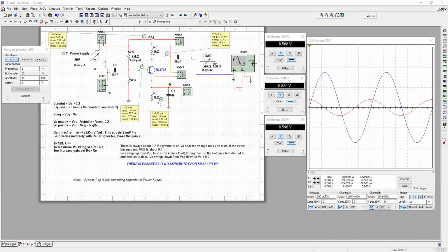We're going to set the current through the BJT using this voltage divider. The voltage at the 5 kilo ohm resistor is passed on to the base emitter and RE. So I can actually set the value of the collector current by setting the value of RE here.